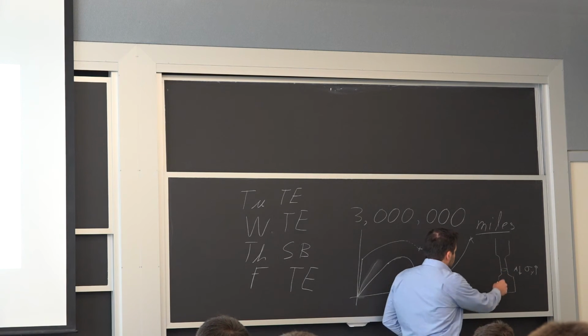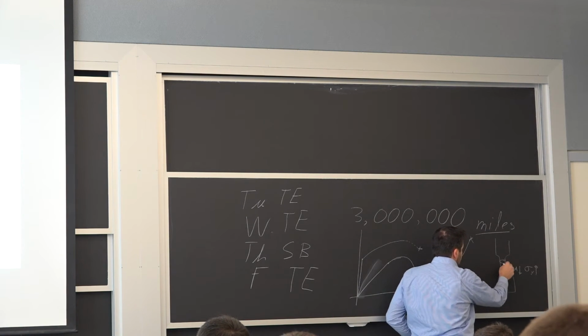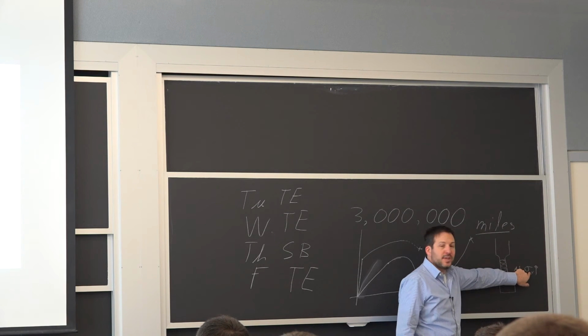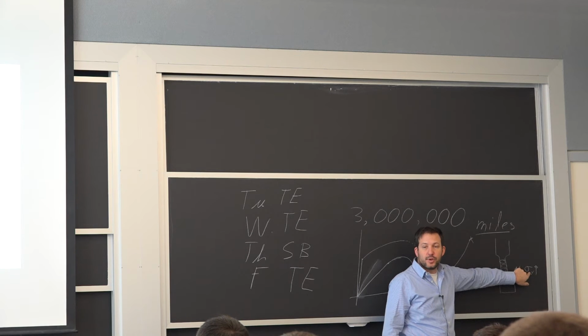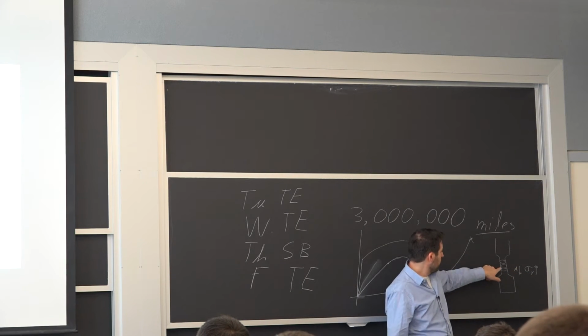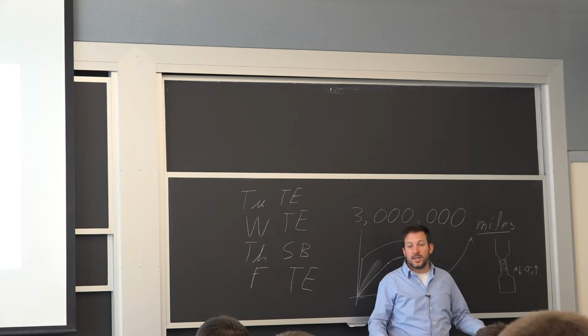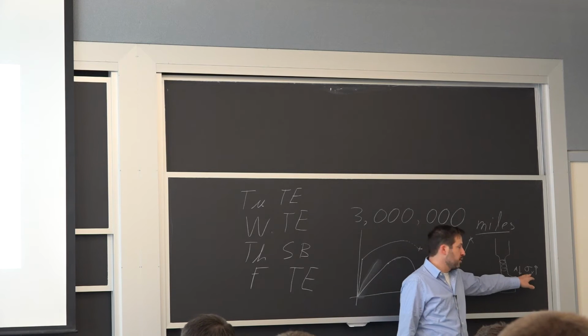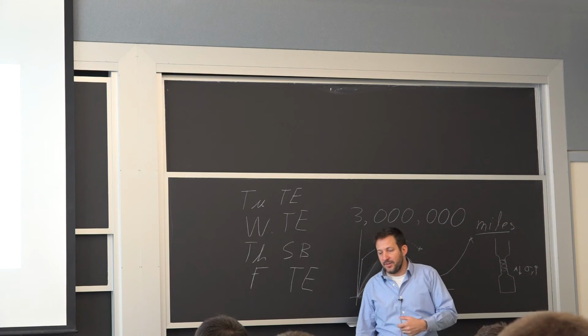And I'm deforming now in the other area, the same thing happened. Now, there will be a point where I don't have that much of an increase in my yield stress with deformation. So when I have this little perturbation of a local reduction in the area, it localizes. That's what necking is. So it's still going up, but not enough. It necks.